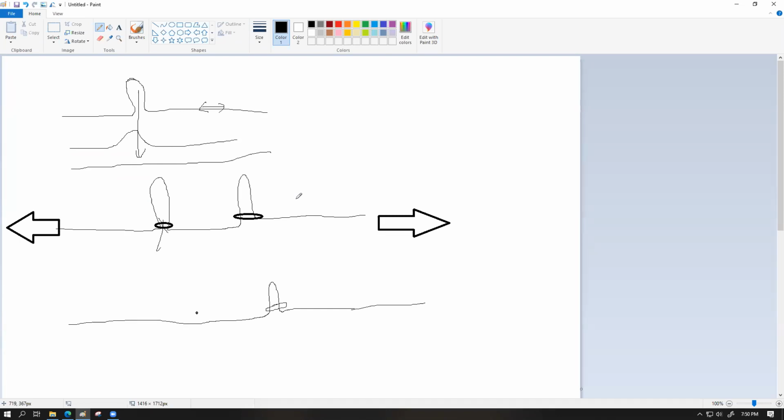I mean, let's say you are making a metal piece by heating it up. Did you do a uniform temperature gradient through the entire piece up to, let's say, the 10th or 20th decimal place? That's not possible. The cooling pattern of individual segments of the metal piece would be different no matter how carefully you do this. This would ultimately make a variation in the internal strength for different cross-sectional pieces, because how the metal would behave under stress is highly dependent on how it was created in the first place, or how it was heat treated in the first place.